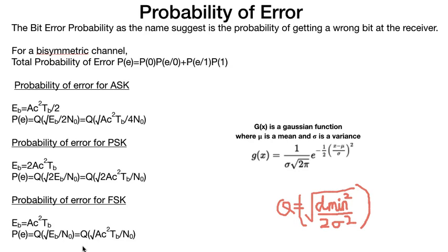In this Gaussian signal, finally you will get your X value; your mu and sigma will be known to you in the question, and you can calculate the value of probability of error eventually. So this is a very important topic, and most people get confused about how to calculate probability of error of a digital signal, of a carrier modulated signal.